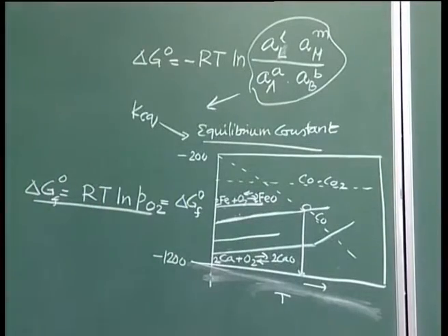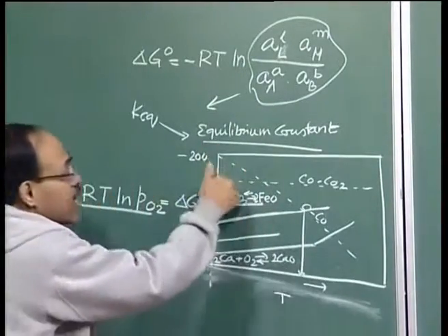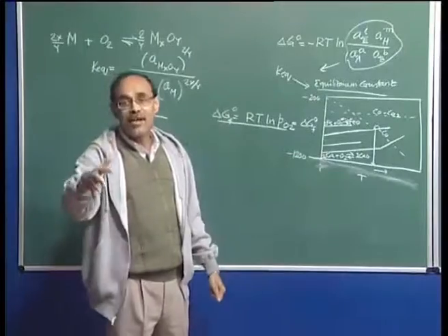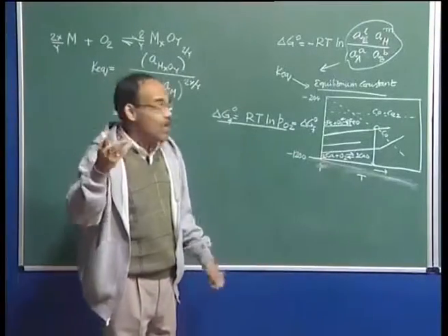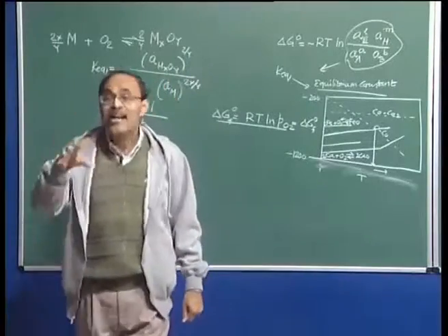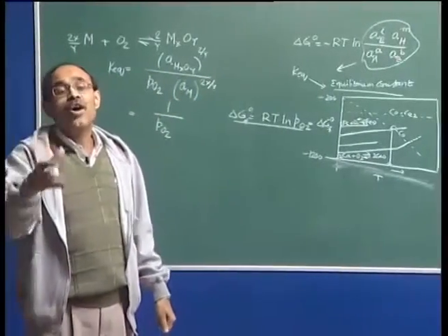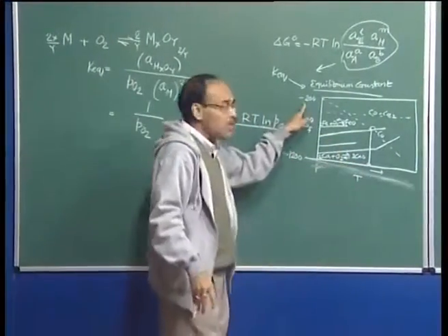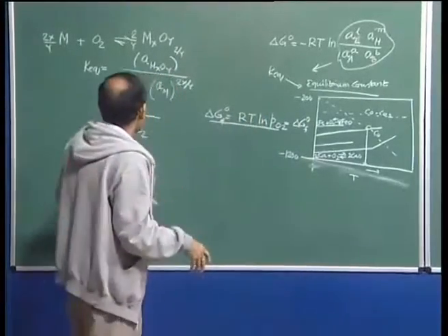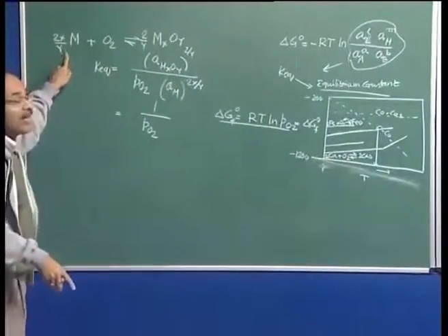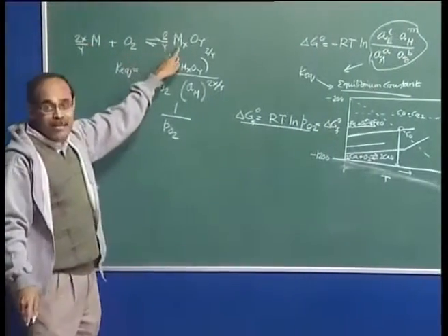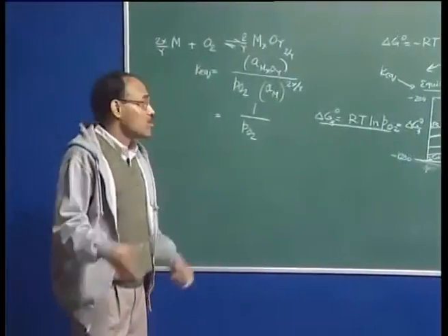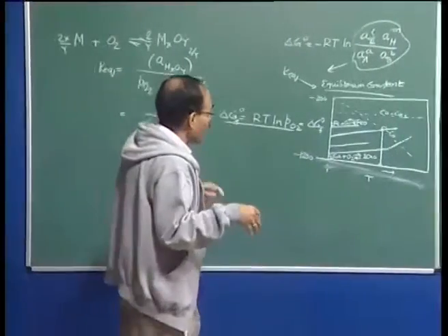Now we see that the carbon monoxide line intersects the Fe/FeO line at 800-900 degrees centigrade, but it intersects the alumina line at more than 2000 degrees centigrade. That's why, by looking at this diagram, we can immediately conclude whether carbothermic reduction of a metal oxide is possible or not. Similarly, we have sulfide diagrams also. Per mole of sulfide, we can find the standard free energy change, where we take a metal, take sulfur gas, and form metal sulfide, and exactly the same sort of graph can be produced. It is known as the sulfide Ellingham diagram, which gives us important clues regarding pyrometallurgical or sulfide smelting processes.